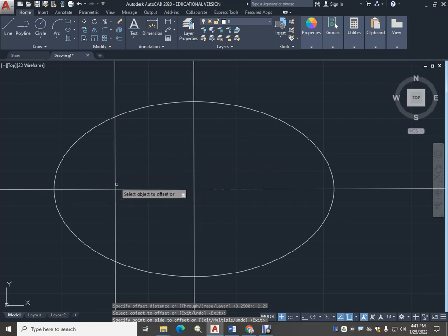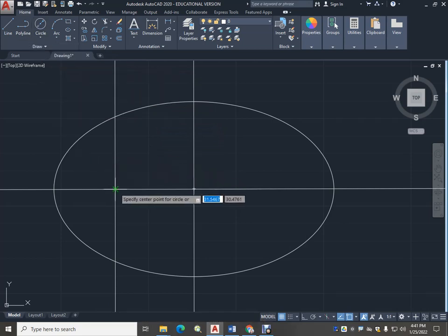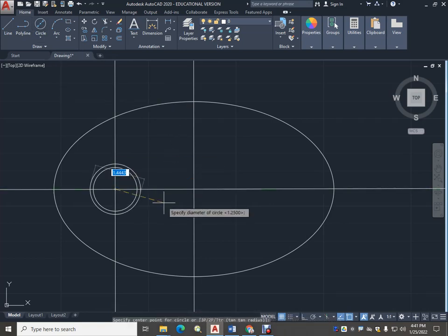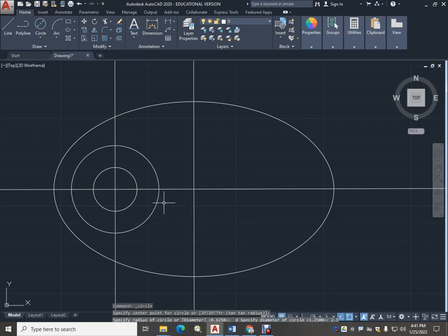The shaft hole is set up to be 1 1/4 inches, so 1.25. And then the outer collar to that is set up at 2.5. So this is where our drive shaft will go through. This will be the hole, and we'll eventually come back and put a keyway on here to lock the two together.